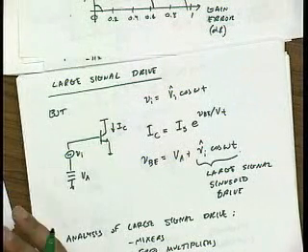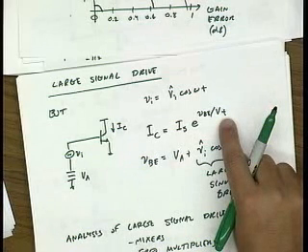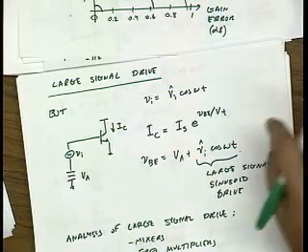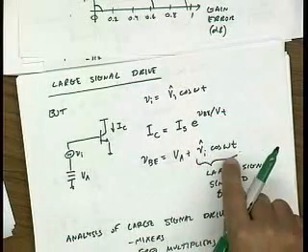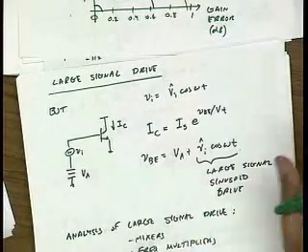But the signal would have to be relatively small relative to Vt for the power series expansion to be valid, right? Otherwise, I'd have to carry 100 terms. So VBE would have to be the signal component, V input, should be smaller than Vt, roughly, to make this power series valid.